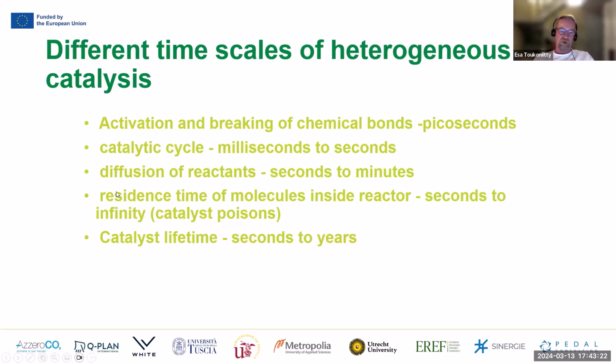Then talking about reactor time scales, when the molecules flow through the catalyst bed, we can talk about seconds. And this is the other extreme: catalyst poisons stick on the solid surface and never leave. That's one way how catalyst poisoning and deactivation take place. And the catalyst lifetime from start till death can be, like I mentioned, a few seconds in cracking catalysts and several years in some of these oil refining catalysts, where those reactors are charged and run for a few years, and then the catalyst is replaced.